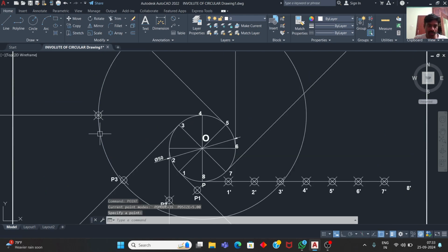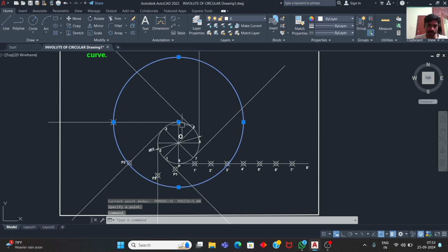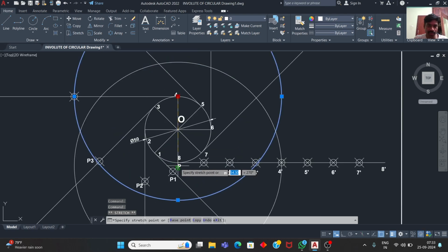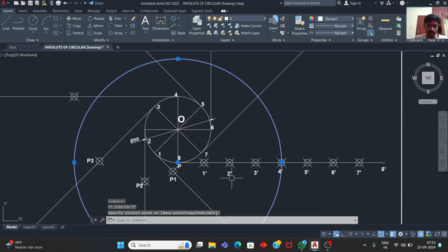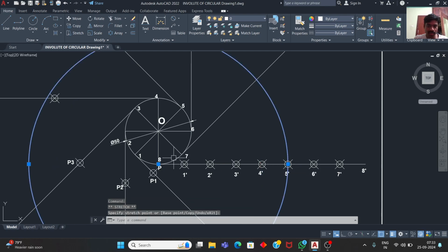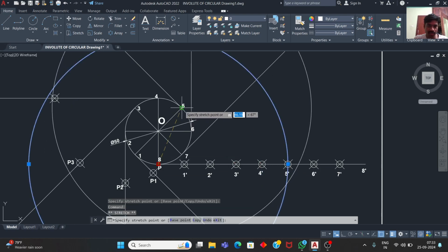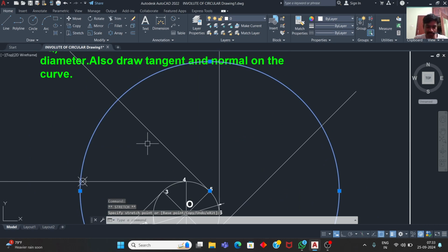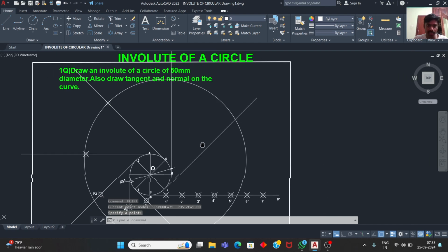However much radius you have taken, you have to mark the point only on that tangent. So be careful while marking the points. Increase the radius now to 5, take the fifth tangent line and mark a point.